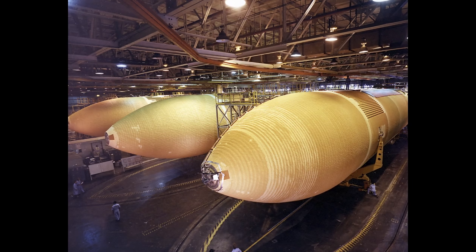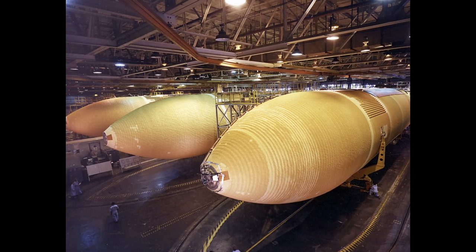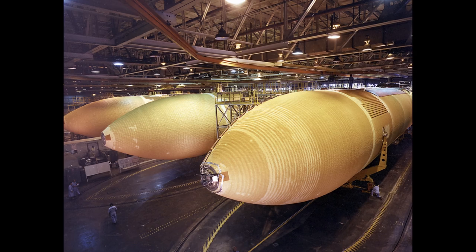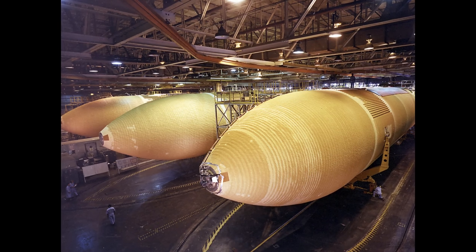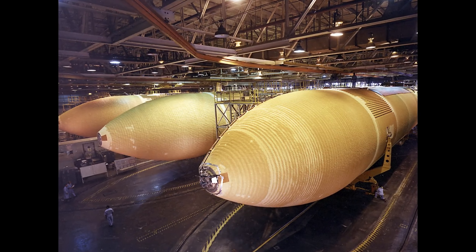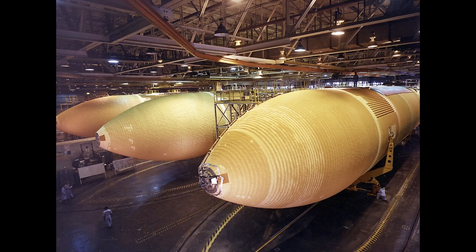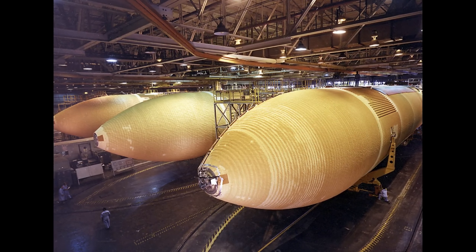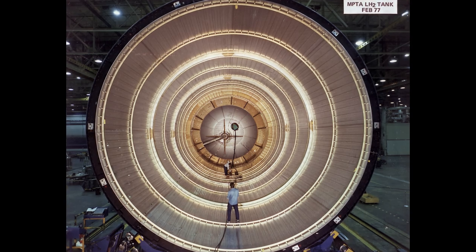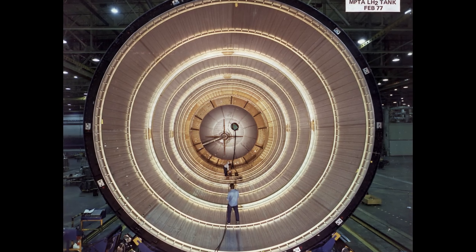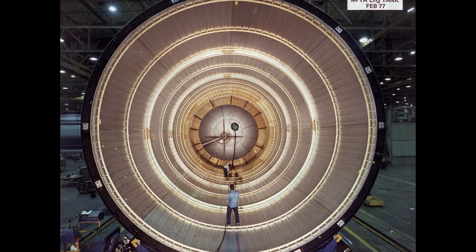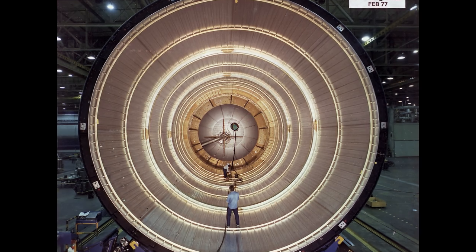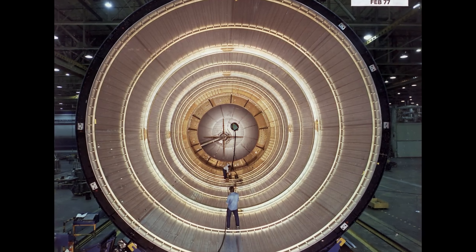With STS-6, the lightweight tank was introduced, used for the majority of the program. These had further reduced weight by eliminating portions of structural stiffeners that weren't needed, modifying the frames of the hydrogen tank, and milling the tank differently so that it was physically thinner and lighter. Next, on STS-91, the super lightweight tank was introduced, which switched to a different aluminum-lithium alloy, saving 7,000 pounds, and was specifically designed to facilitate larger payloads to the ISS.